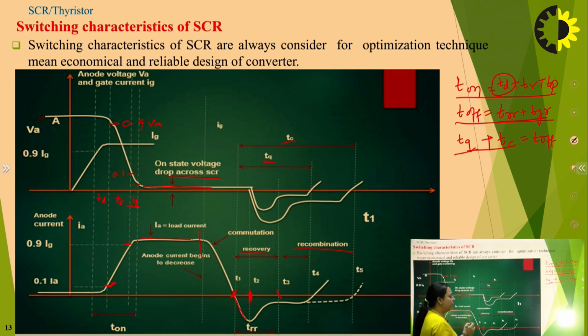Although it will not be good for the circuit, because of recombination, a reverse surge voltage must be maintained across the device. The magnitude of the voltage is not important, but there must be some reverse surge voltage across the device so that the recombination process may take place and excess carriers from the junction J2 may be removed, right?